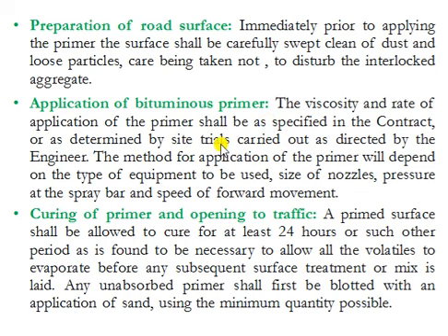Depending upon that, the contractor will apply the primer, and the method of application of primer will depend on type of equipment used, size of nozzles, pressure at the spray, and it also depends upon the engineer's decision.